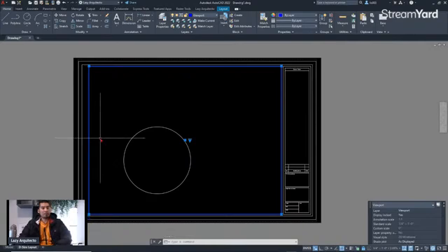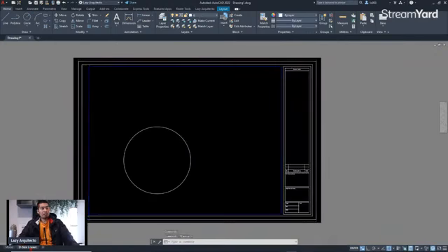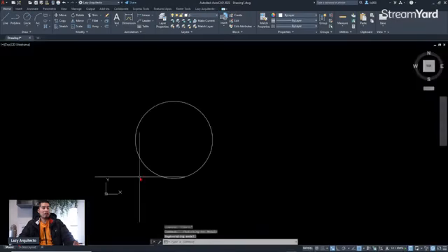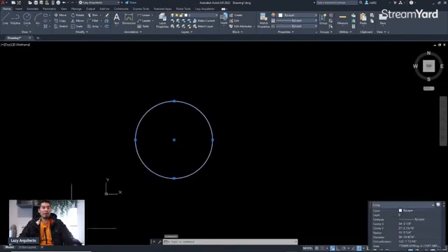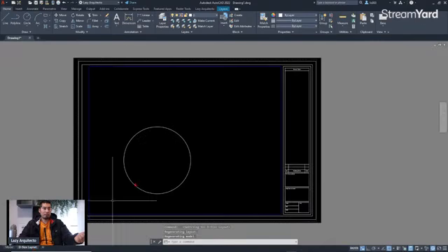But that was a very basic concept of the difference between paper space or layout and model. Here in model, of course, you're gonna draw everything or mostly everything, like 99.9% of your objects, your house, your building, and so on, will be drawn here in model. And then again, here in paper space or layout, you will print.